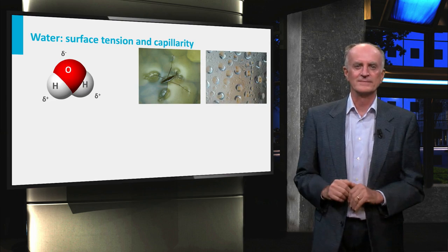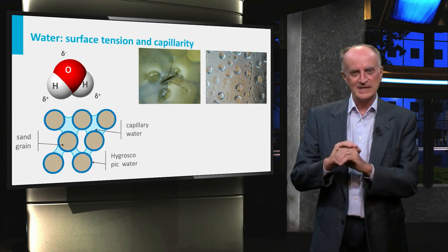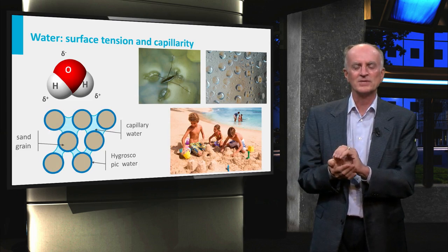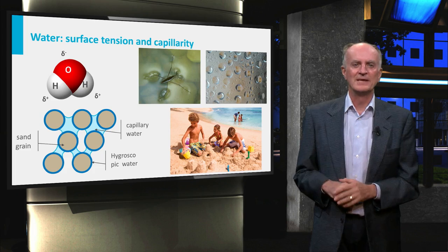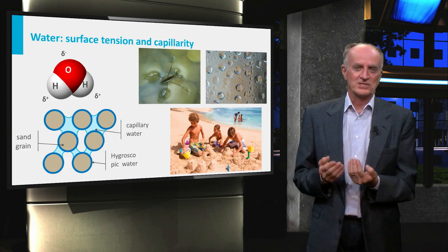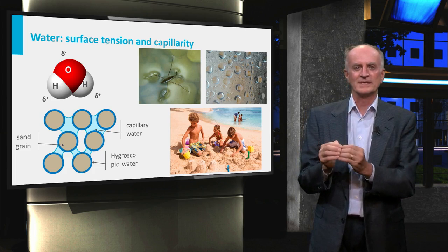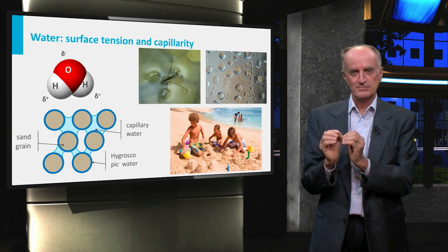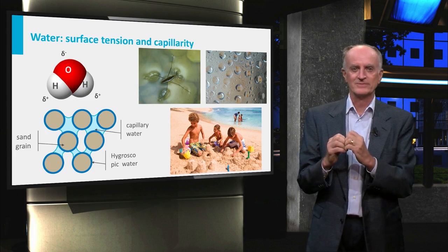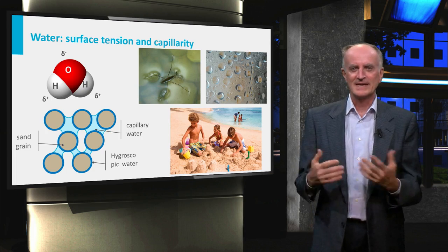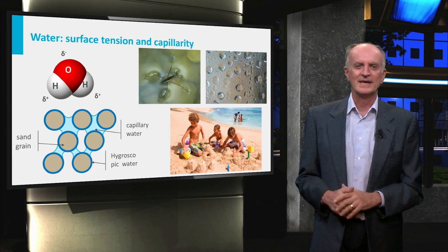of the surface tension. In average types of rocks, things are different, and water spreads easily, forming a thin film of fairly homogeneous thickness over all grains, between 0.1 and 0.5 micrometers. This seems not much, but it means that grains will be water wet even if the rock is well above the water table. It means also that some of the smaller pores between the grains will be occluded by water, holding the grains together. Children or adults alike, building castles on the beach, know very well how to exploit capillary effects to improve their building and achieve steep walls.